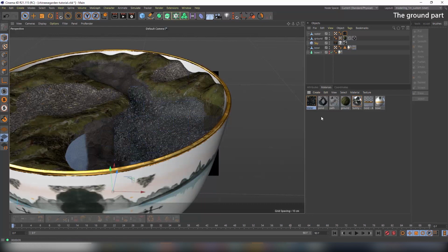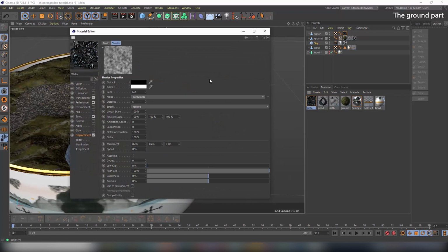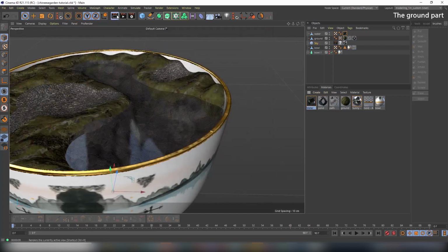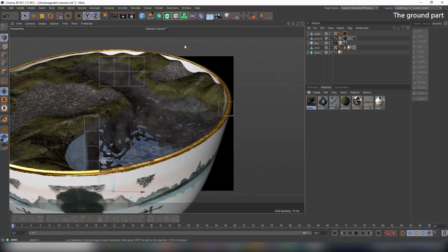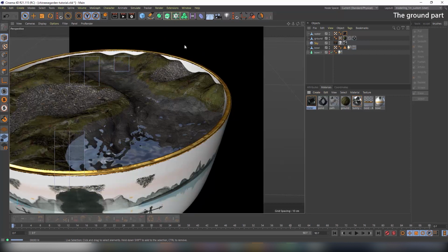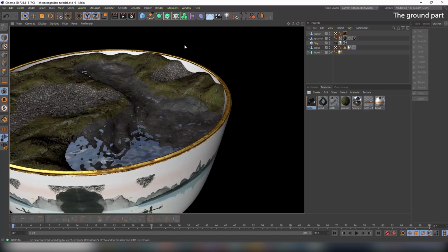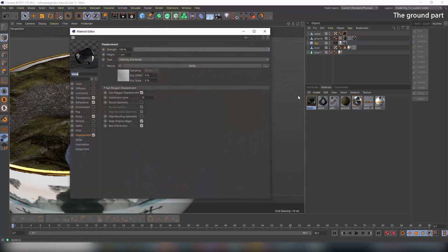Okay, and we've got a really small wave, so we have to go to our texture and put the global scale of this noise, not 100%, but let's try 2000. Yep, it's getting better. Still, I think the height of our waves is too much. So you need just a slight feel. So maybe something like this, and maybe just let's try 6.